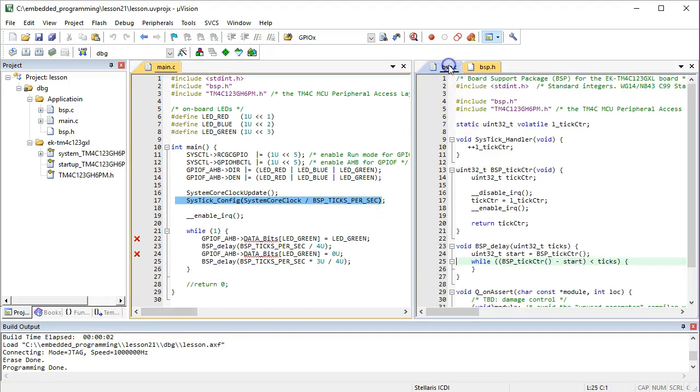The system interrupt handler simply increments the local L_tick counter variable, which is declared both static and volatile. The volatile qualifier was introduced back in Lesson 5, but let me quickly remind you that when you declare a variable to be volatile, you are telling a compiler that the variable might change unexpectedly, even though no currently performed program instructions change it, which is exactly what can happen when a variable is modified in an interrupt.